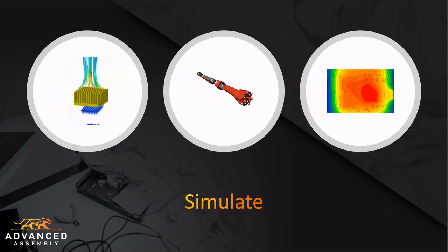If you are designing for harsh environments like high altitude, space, downhole locations where convection isn't available to cool your board, you should really simulate your design. Simulation is going to provide reasonably accurate information of how your board is going to behave in the real world. Tools that I prefer are SimScale, SolidWorks, Autodesk, Mentor. All of those things are going to provide a variety of simulation methods. And really what you choose depends on what you can budget and how accurate your simulation needs to be.